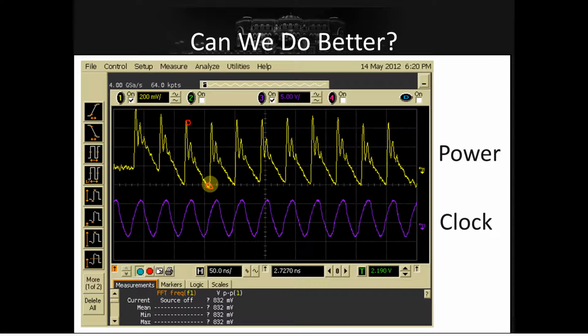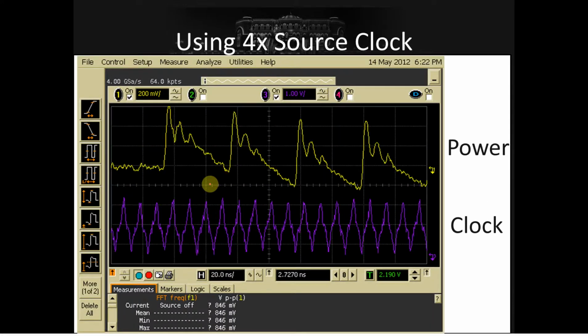So if you're only sampling at 200 megasamples per second, you're not going to get that perfect sample that's consistent for every clock cycle, especially for these hardware implementations when we only have 10 or 11 cycles that we can use at all. We need to make sure it's consistent. And it may be that there's only one point you even really need, which it actually ends up to be the case for a lot of these, but you need to make sure that point was just at the right time. And to do this, we just sample really fast and throw away everything that was wrong.